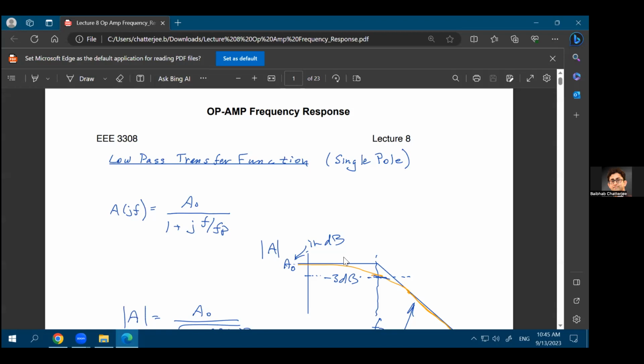Now, in Laplace domain, some of you are also very familiar with Laplace transform. So in Laplace domain, you represent this as S times L. Basically, S is your j omega. S is equal to j omega. And that's the Laplace term that you consider when you are doing any kind of Laplace transform. So if you do the same thing here, this becomes 1 upon SC. So for a capacitance, the impedance is 1 over j omega C or 1 over SC. So that's the impedance of this capacitor as a function of the frequency.